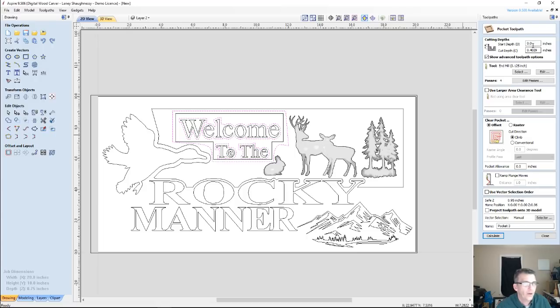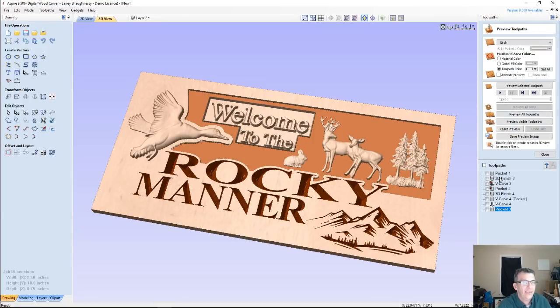That is going to be 0.4029, which is fine, or I could just save some time. We're starting from 0.2616, the same depth that we're starting from. And then if I go 0.4884 minus 0.3471, my current Z plane, that's my depth of cut. I can calculate that toolpath, and it should cut around all that area and get rid of that lip.